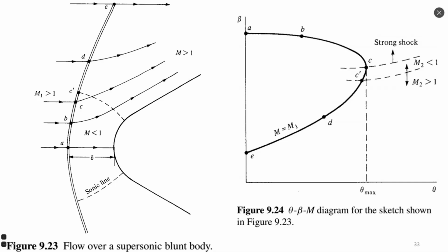But we can always calculate several aspects of this. It's relatively simple to predict the delta thickness, or distance between the body and the shock wave. This delta, the minimal thickness, can also be calculated numerically, but the model is not so complicated. If one of you would like one day to calculate such a structure, I could recommend literature to read. I think there is no analytical model to calculate it directly, but there is a way of solving a number of ordinary differential equations to calculate such a distance.